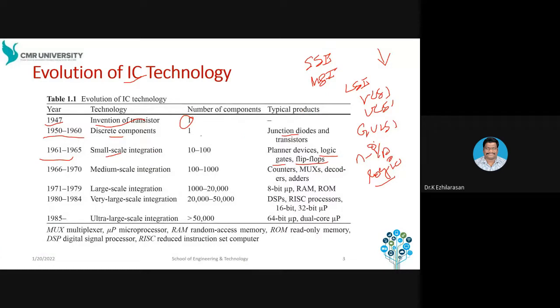So to implement an N input logic gate with the help of CMOS, we require 2N transistors in total, where N is the number of inputs. For example, consider implementing a 2 input NAND gate.